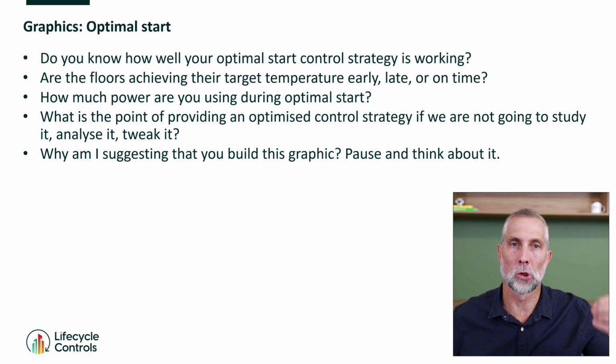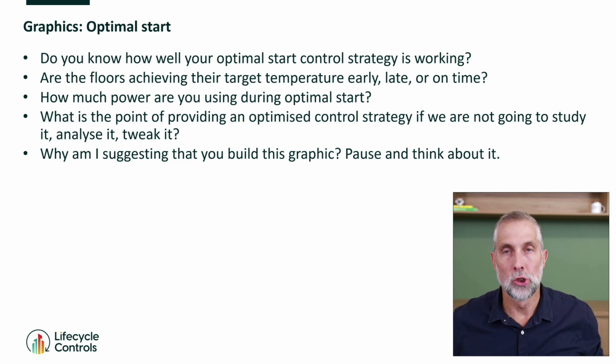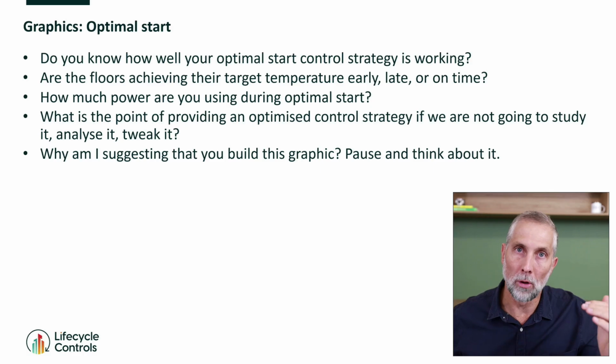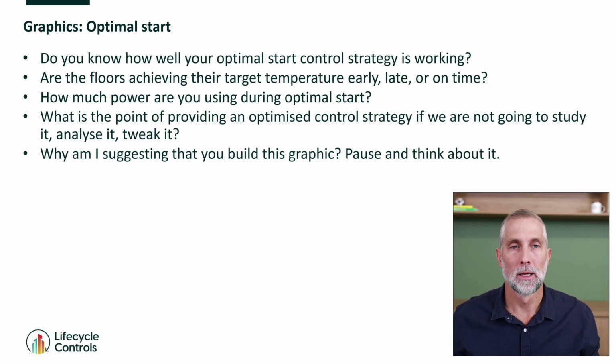And that's why if you do the optimal start course, it talks about just preheat the building to 21 degrees Celsius and pre-cool the building to 24 degrees Celsius. Those are the least conditioned temperatures. Do not heat the building to 22 degrees Celsius if 21 is going to meet the contractual agreement. And don't cool the building down to 22 if cooling it down to 24 meets the contractual agreement between the landlord, the building owner, and the tenant. So optimal start's kind of difficult because you're always fighting the battle of comfort control and achieving that using the least amount of power possible.